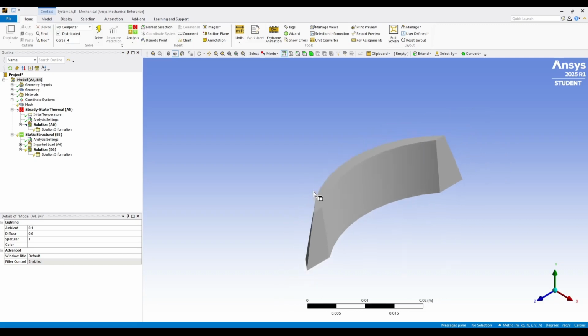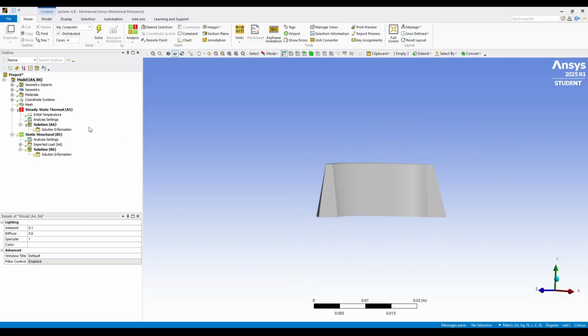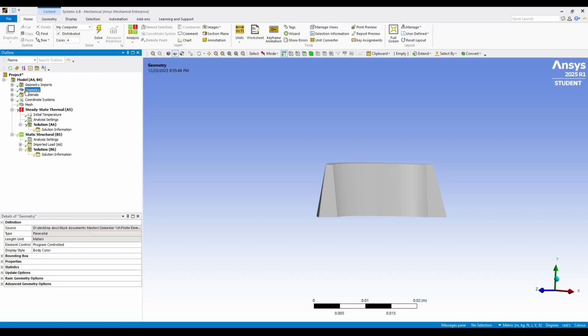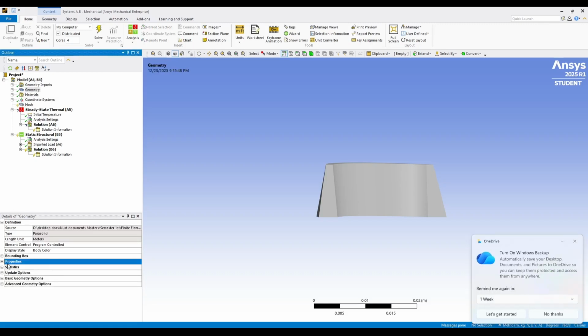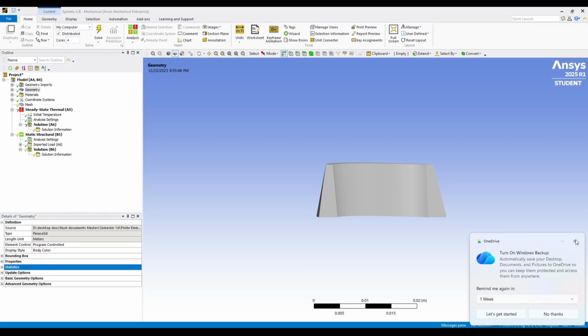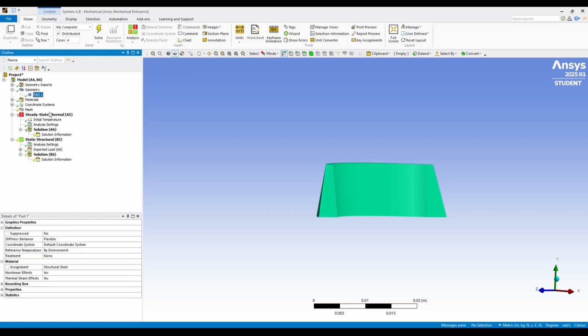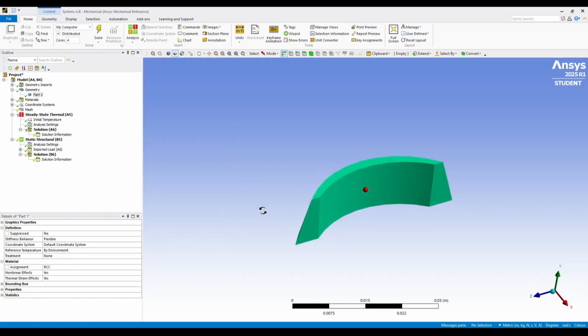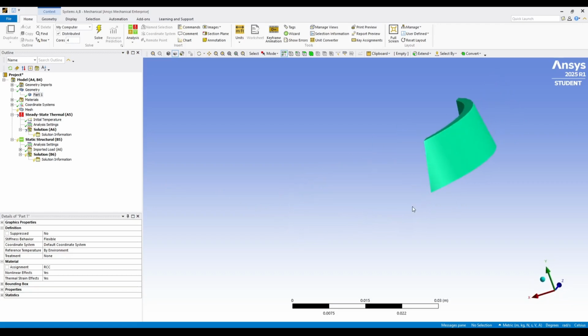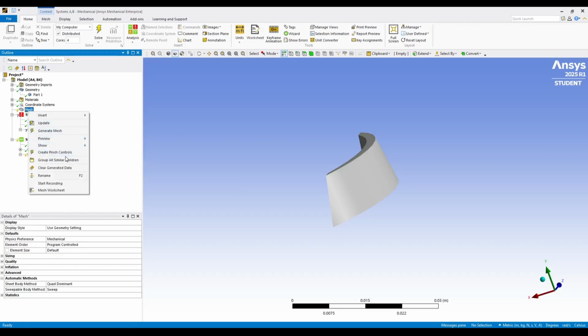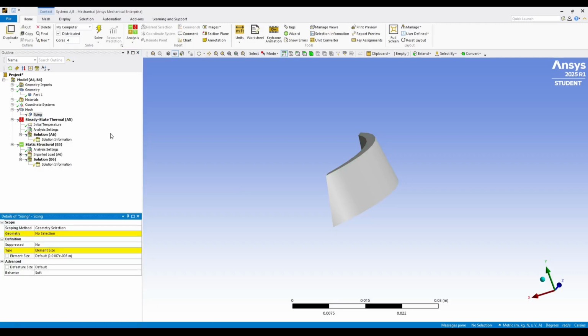perspective. A steady-state thermal analysis is then carried out to study the effect of temperature differences across the dam body. Different temperature conditions are applied on the upstream and downstream faces to simulate environmental and seasonal variations. This analysis provides the temperature distribution within the dam and highlights thermal gradients that develop across the structure. These gradients can induce thermal stresses that significantly affect the overall structural response.